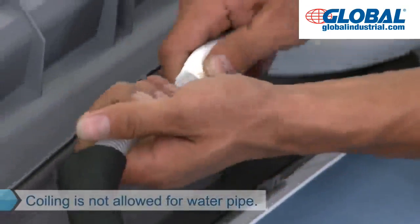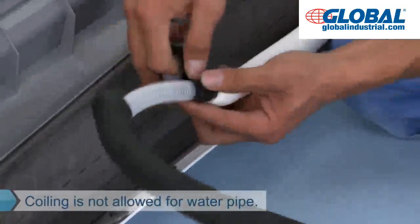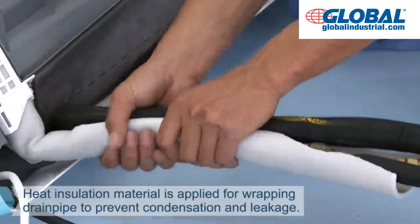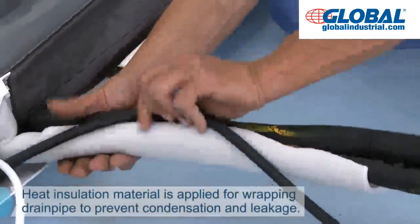Seal drain pipe interface with adhesive to avoid loosening and leakage. Cooling is not allowed for water pipe. Heat insulation material should be applied for wrapping indoor side of drain pipe to avoid condensation and leakage.